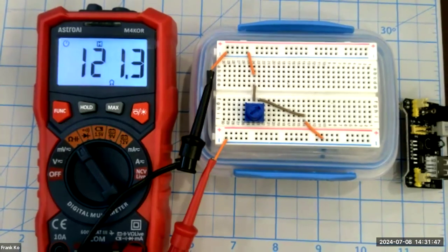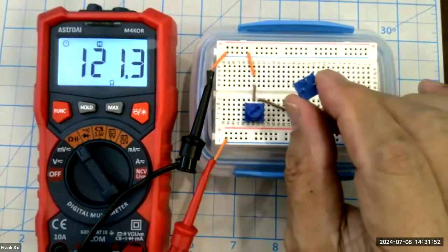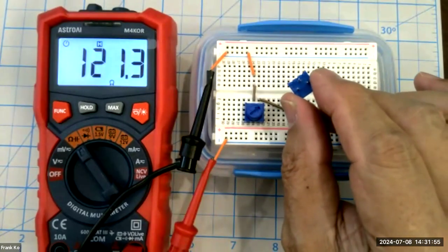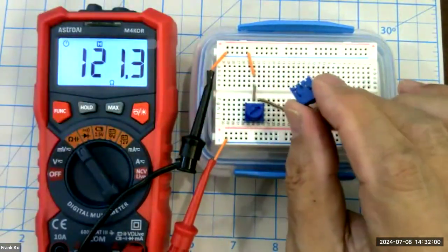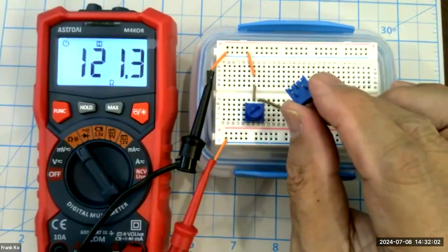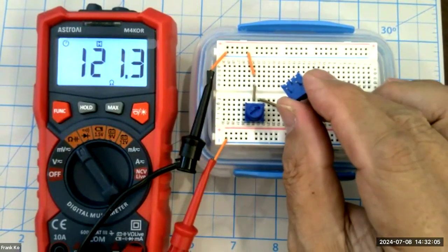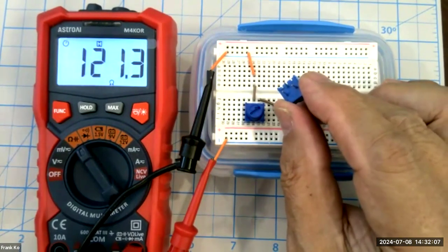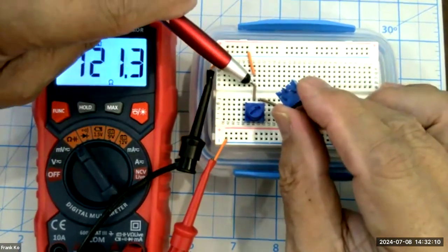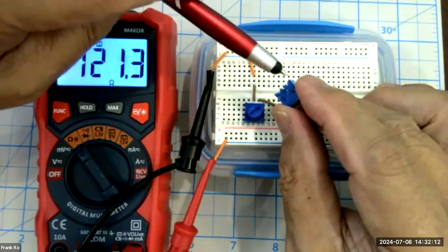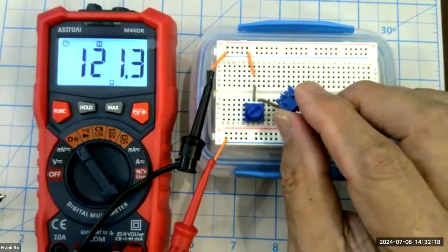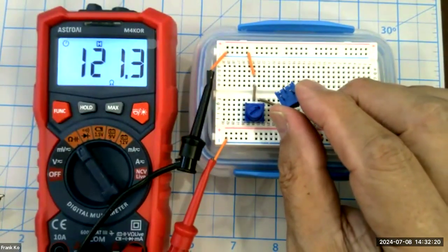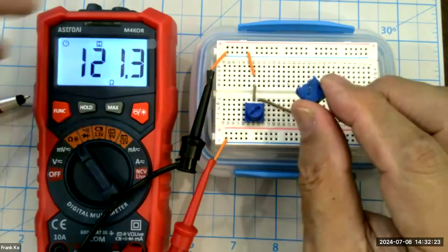The potentiometer, and I'll show you in another slide in greater detail, but let me just show you the underside of the potentiometer. The underside shows 3 pins, and the connection for variable resistance is between the middle pin and any of the outside pins, either one of the outside pins. And so what I've got is the brown jumper wire to the center pin, and on one of these outside pins is a connection of this other jumper wire, so that I'm only using the center and one outside pin for dialing the amount of resistance that we need.